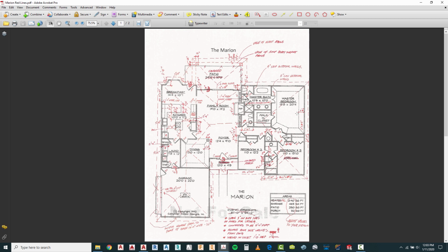I'm now going to use the offset command to start setting up each one of these walls, working my way around the house, switching from exterior to interior layout. The first part of this assignment is that we are going to lay out the exterior and the interior walls without doing any openings yet, with 1 or 2 exceptions.